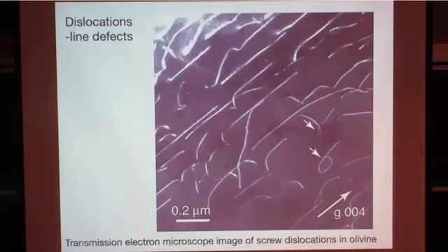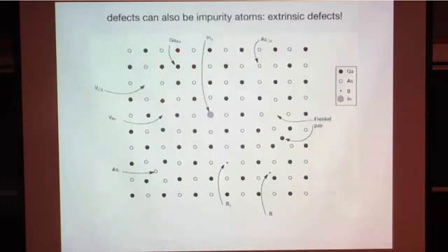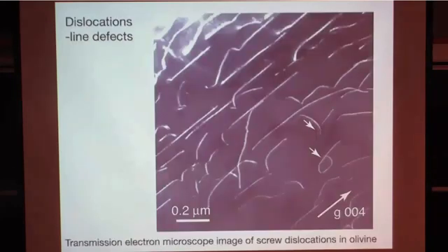So, point defects: you can thermodynamically calculate how many of these you have, right? That was the balance between entropy and enthalpy. There's a different type of defects. These are point defects. You have line defects, and Patrick will be covering them. These are dislocations. As you can see here from the scale bar, these are more macroscopic, so we can't describe them by thermodynamics anymore. We don't have a thermodynamic reason for having defects. It turns out these are directly created by deformation itself.